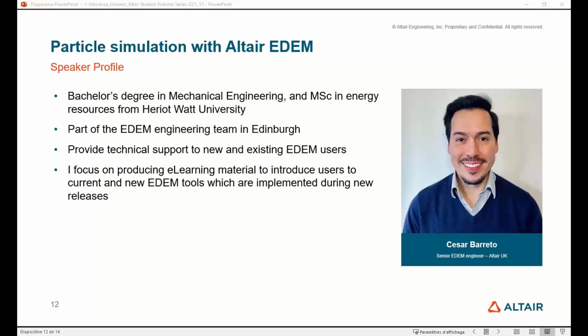One question is, can we capture temperature in EDEM? Yes, the answer is we have different contact models in EDEM, and one of them is temperature. So you can transfer the temperature between the geometry and the particle, or the other way around, between the particle and the geometry, and between particles. Of course, temperature is quite complex, and it all depends on the kind of simulation you would like to do.